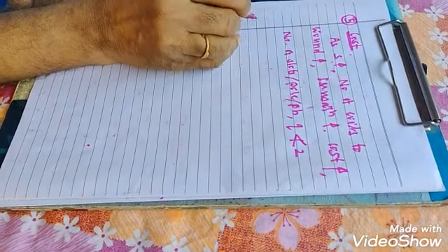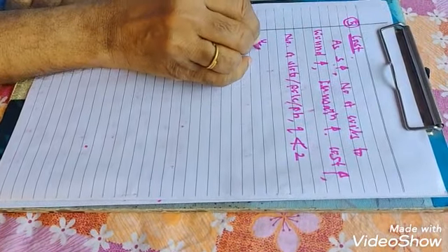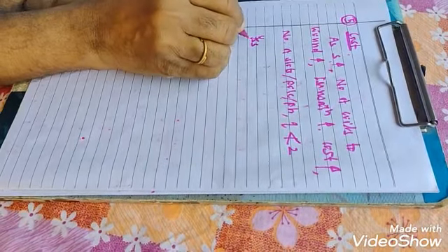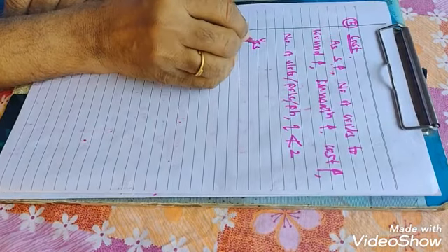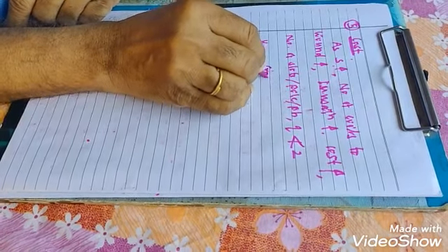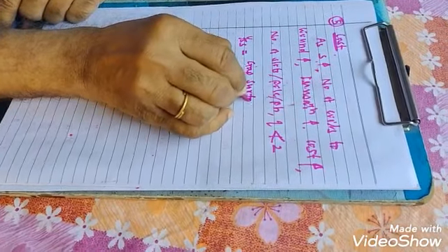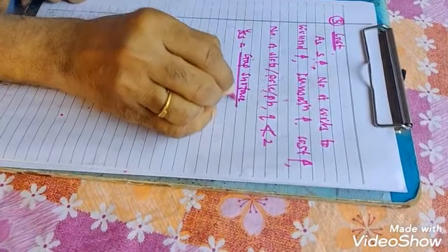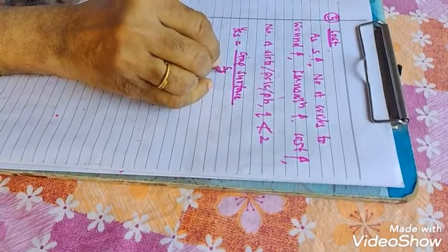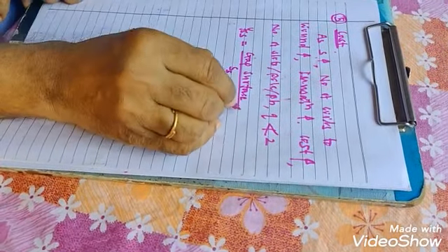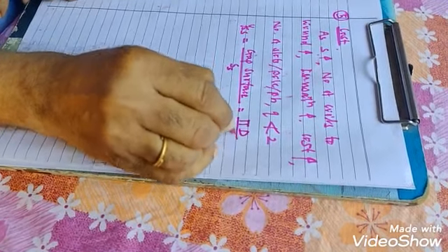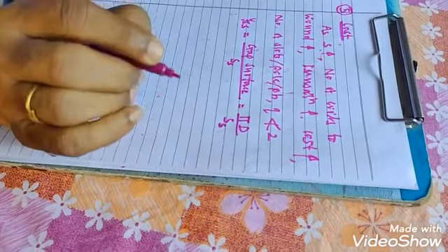Then the stator slot pitch, YSS. YSS is the slot pitch, as it is for the stator. This is equal to the gap surface upon the total number of stator slots. Gap surface is pi d. So YSS is pi d upon stator slots SS.